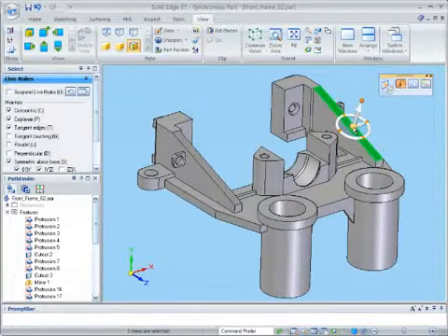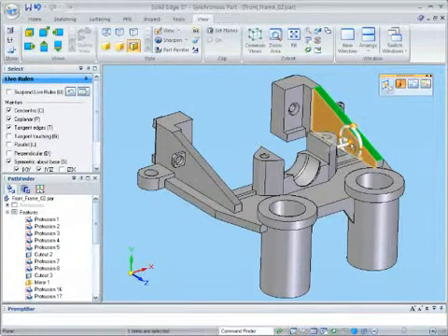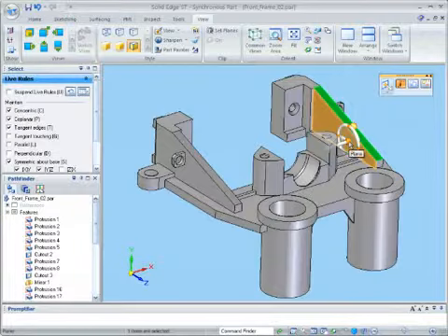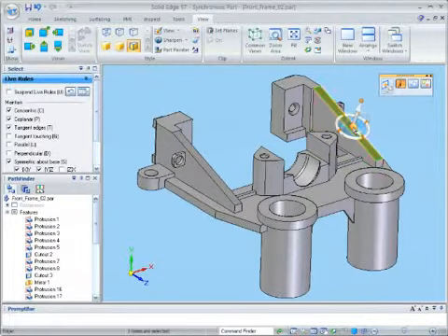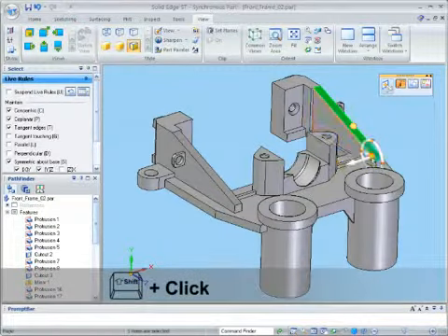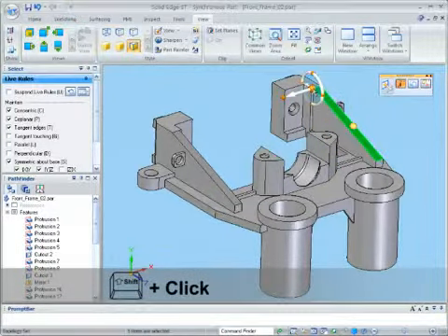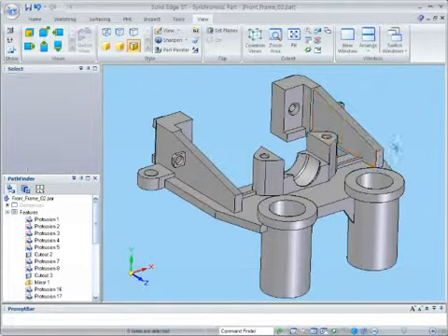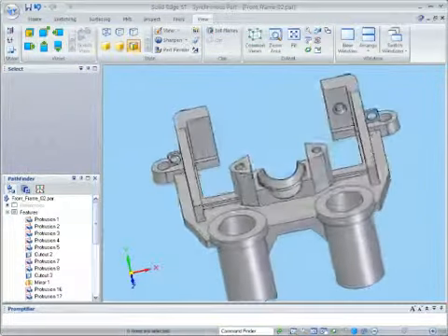To rotate a face, select the face to be rotated, then reposition the steering wheel by dragging the origin so that the torus is perpendicular to the face. You can see that the steering wheel snaps into key points and reorientates automatically. By shift-clicking on the origin and then dragging the steering wheel, its orientation is preserved. Other modifier keys can also be used.